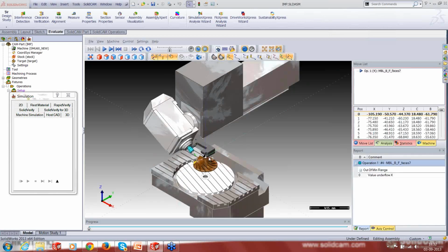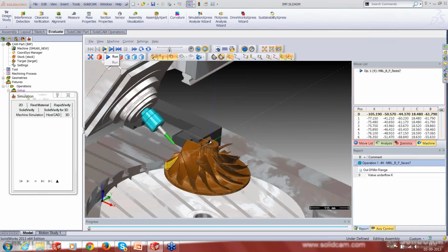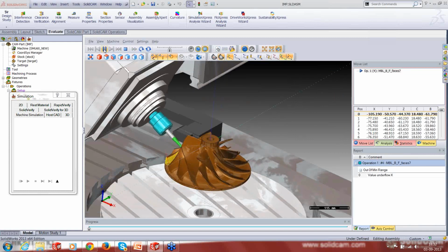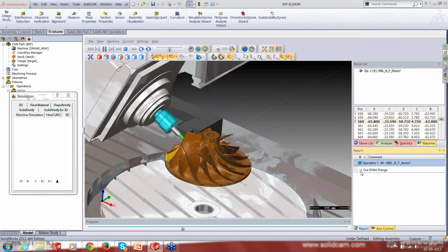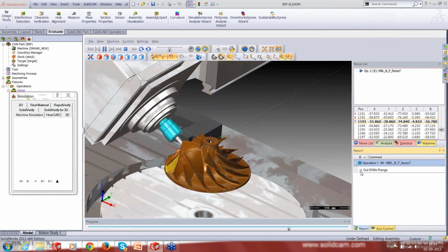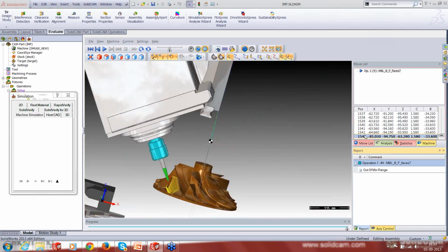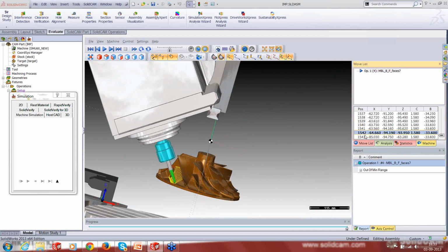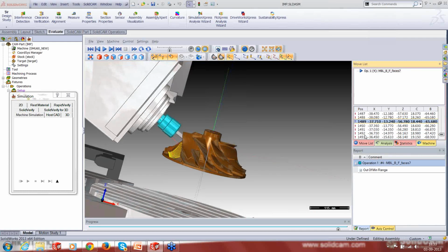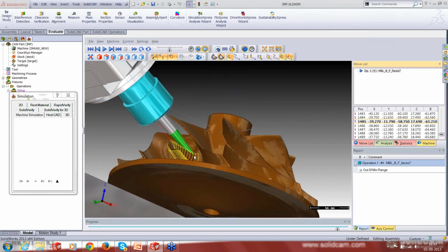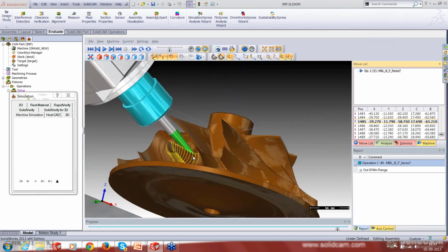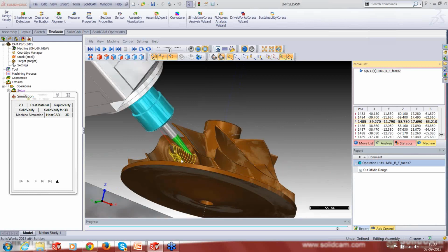We have the toolpath. Let's quickly run the simulation. Absolutely no gouges. So you can see how it handled this area out here. It's pretty tricky. It changed the lead lag and moved the tool away from that surface. So it has worked. I just had to select the check surface and select how much I want to be away from this check surface. The gouge check is already done.